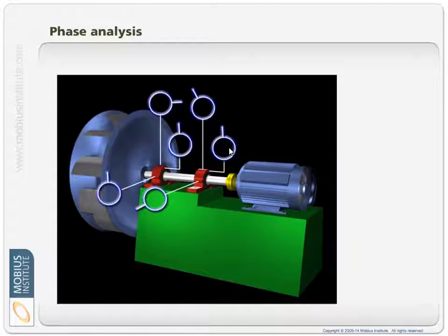The challenge with phase is how you measure it. Now, the simplest way is to have a 2-channel analyzer, carry that second accelerometer with you, because you usually just take single channel measurements on a machine, and when you suspect a problem, you put, for example, one sensor on top, one sensor on the side, and say, what's the phase difference at the running speed between these two locations? And if it's somewhere around 90 degrees, aha! Now we take one sensor and put it in the axial direction, another sensor in the axial direction here. We say, what's the phase difference between these two locations at the running speed? They're pretty much in phase with each other. And so that's all you've got to do.